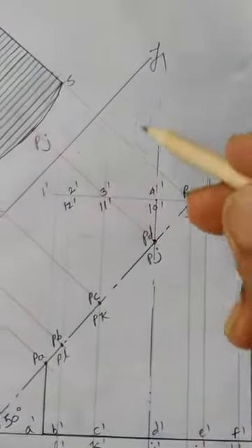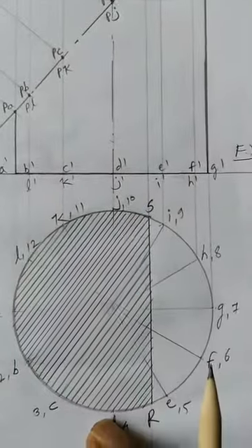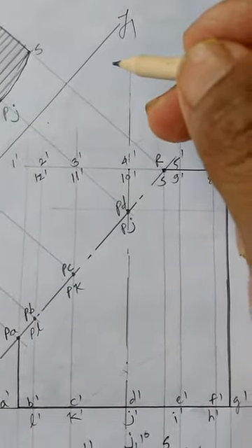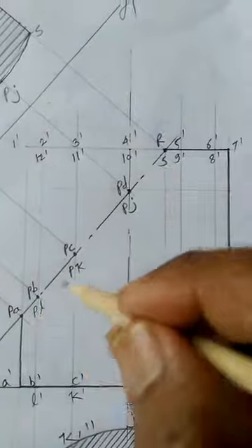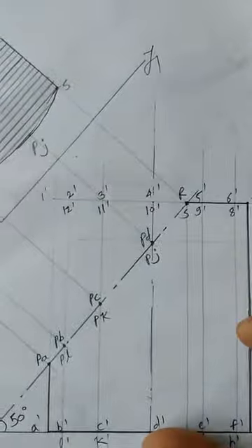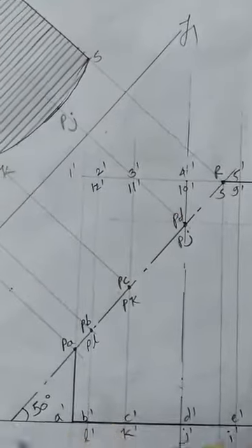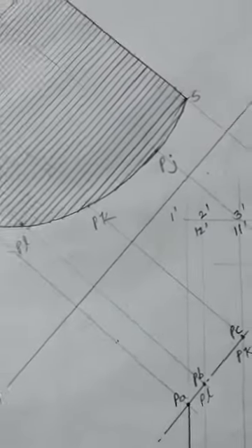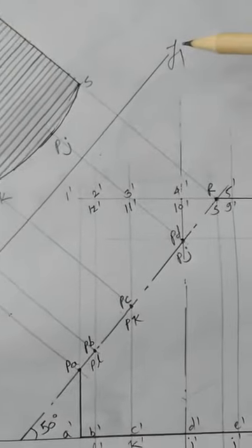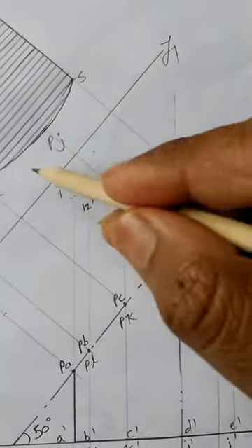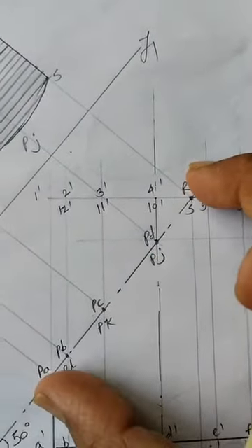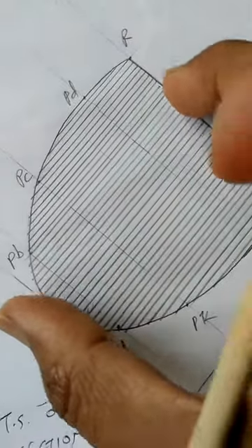And when we observe from top, it is going to reflect its apparent image, because we know that the line of action or the direction of observation is not normal to this cutting plane or this surface. That's why it is reflecting its apparent image. Now we have to get the third solution, that is the true shape of the section. That's why, just parallel to this cutting plane, outside this object, we draw this artificial platform, that is the x1 y1 auxiliary reference line. Now you have to observe from this direction. Naturally this direction of observation is now normal to this surface which is getting cut, so it is going to reflect by default its true shape of the section.